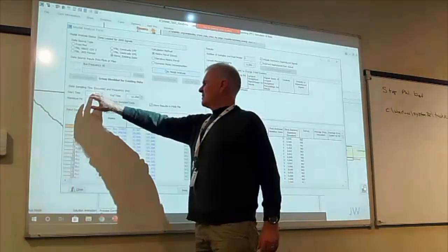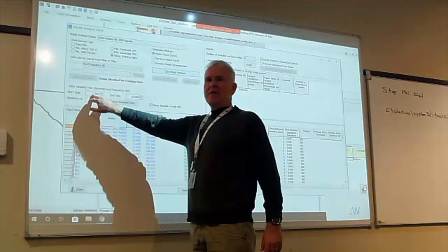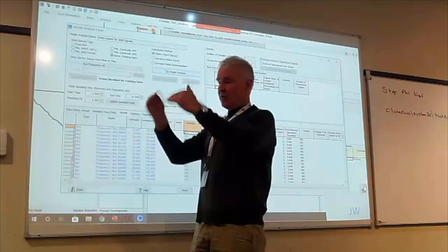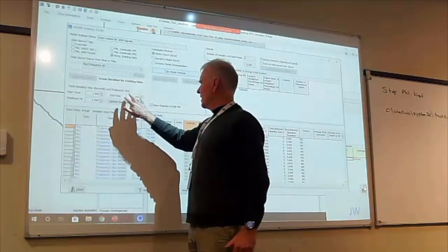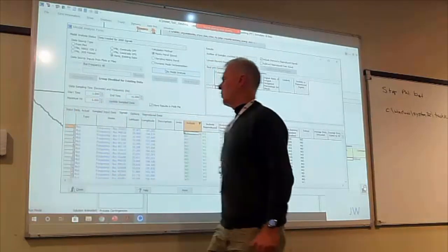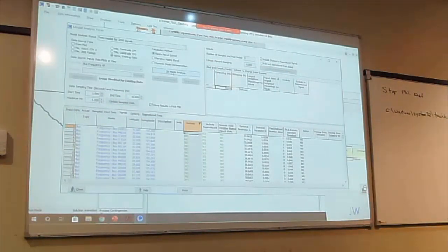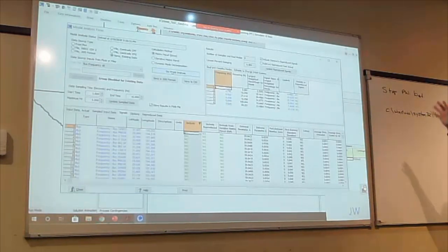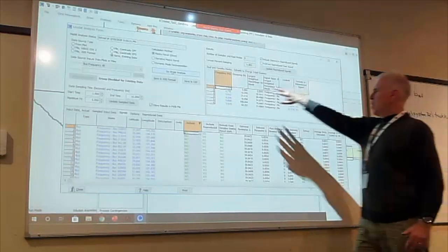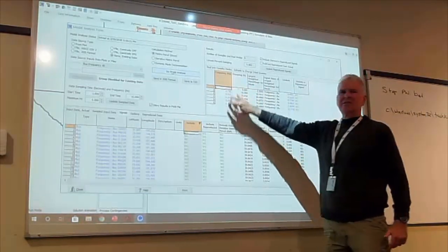It's automatically set your start time to be 1 there, which is the time where the last event occurred. It's going to end at 15, maximum hertz is 5, so we should be okay. So just click do modal analysis. It does the modal analysis, and it reproduces this signal using 6 modes.